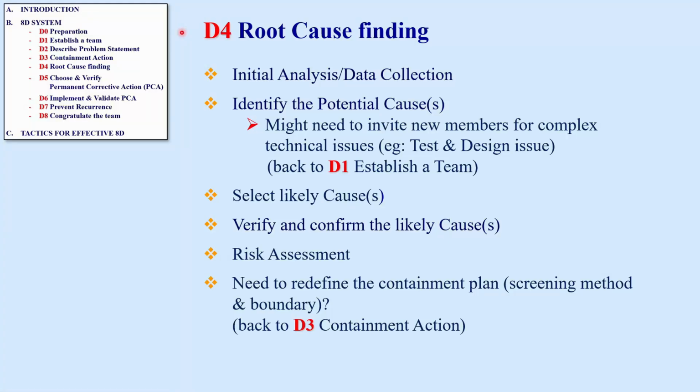D4. Root cause finding. These are the high-level general steps for root cause analysis. First, perform the initial data collection and analysis. From here, brainstorm to identify all the potential causes. For complex technical issues, such as test or design issue, we might need to invite new members.